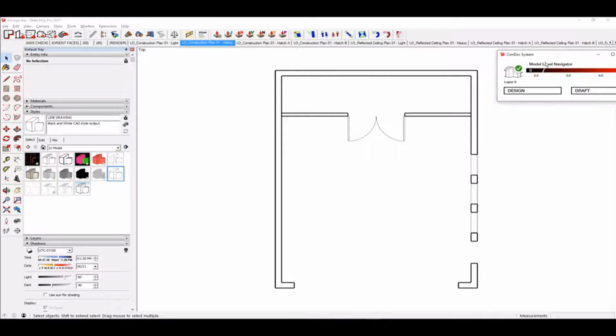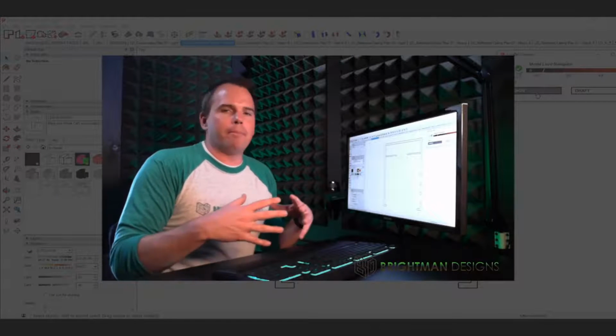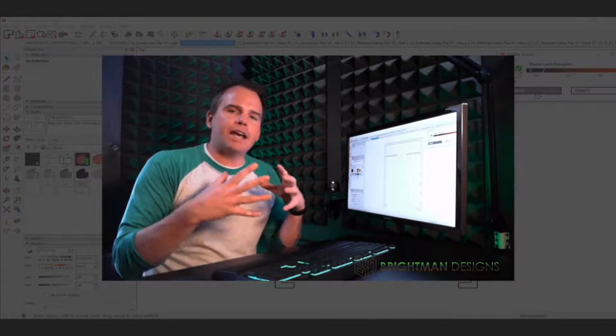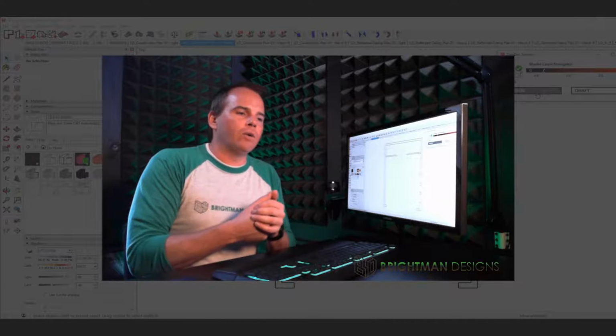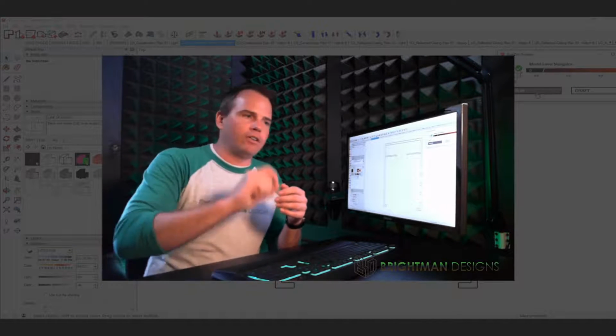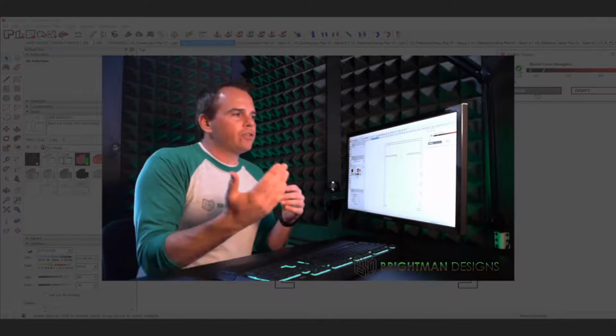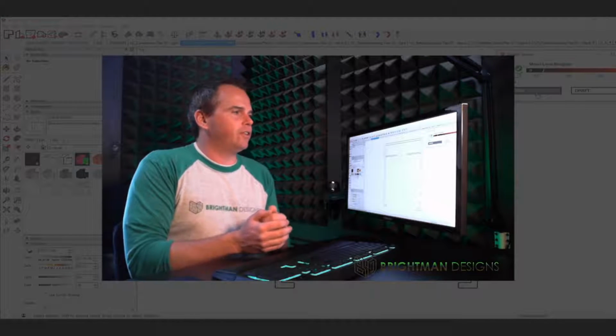So what you could do is, if your consultants don't care about line weights, which most of them don't, they're not too hung up on your line weights, they're going to take your background drawing and gray it out, and then draft on top of it. And they're going to have all their long dash, short dash lines with a bunch of text. So your drawings are kind of playing second fiddle to theirs in that instance.